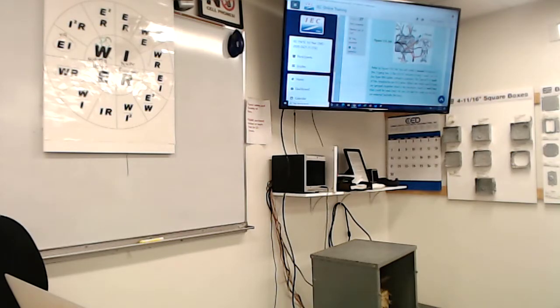Y'all good? So on the equipment, it doesn't pertain to this, but it does look like something they added that's new for grounding conductors. If it's more than 4, it does add to the volume. A quarter volume allowance shall be made for each additional equipment grounding conductor bonding jumper that enters the box, based on the largest. Okay. It's more than 4.